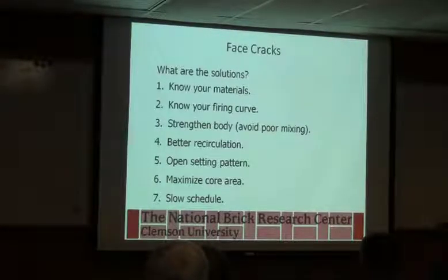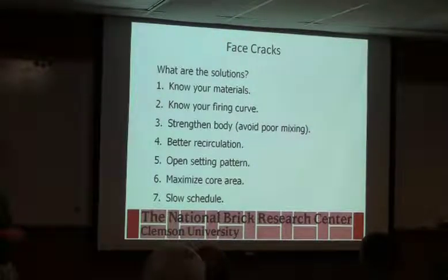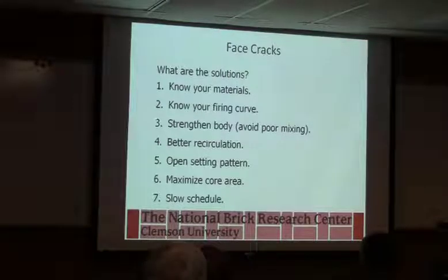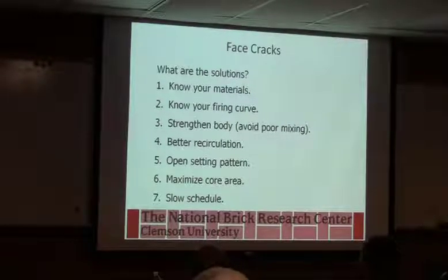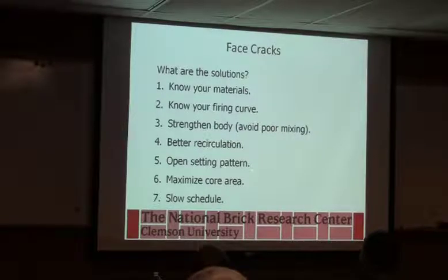Face cracks. What are the solutions? So basically you need to know your materials, know your firing curve, strength of the body, whether to avoid poor mixing, better recirculation, opening the setting pattern, maximize core area, and then slowing the schedule. But again, you've got a schedule, a production rate that you're trying to meet.